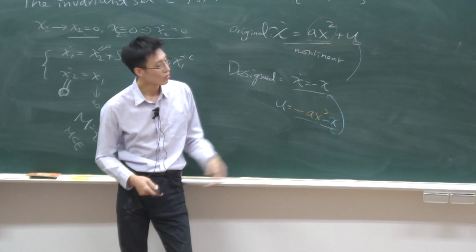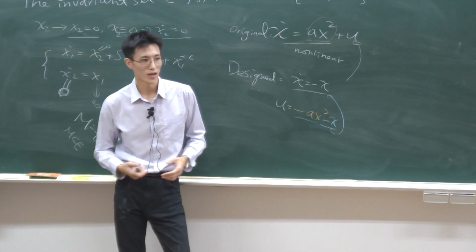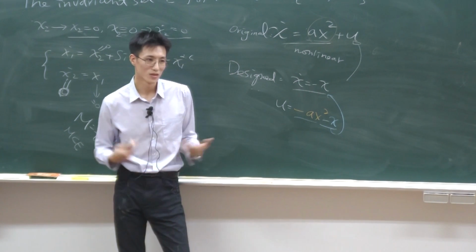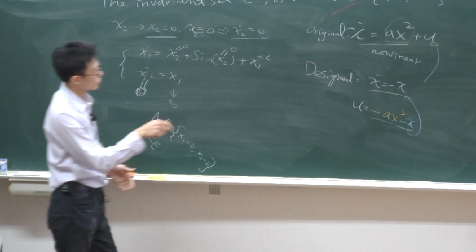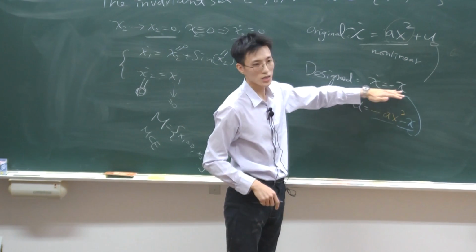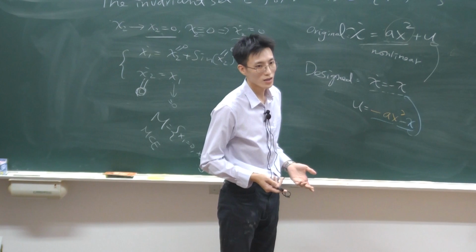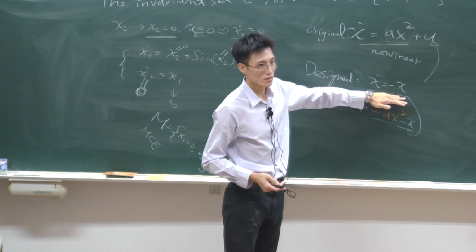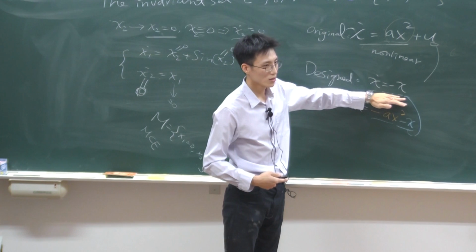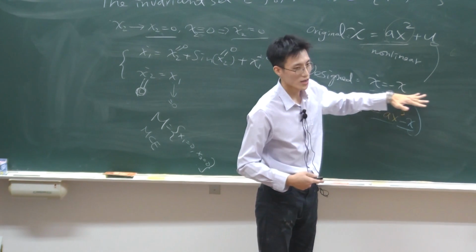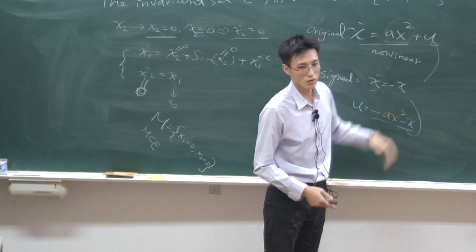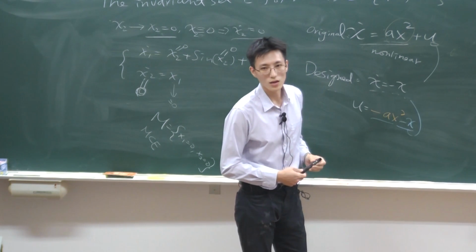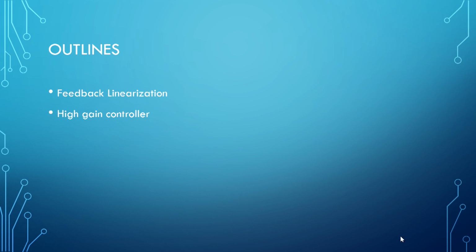You can ask him, how do you know your parameters? That's the first question to ask. Okay, and the answer will be, problematic. But the advantage is once you can change your open loop dynamics to this closed loop dynamics, which is linear, you can evaluate the performance, right? You can always solve the solution of a linear ODE, right? So you know how fast it converges to your origin or to the equilibrium point. Understand? Starting from now, we will discuss controller design.